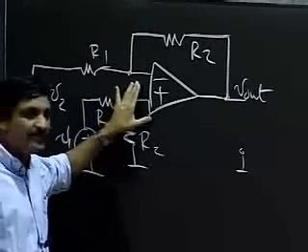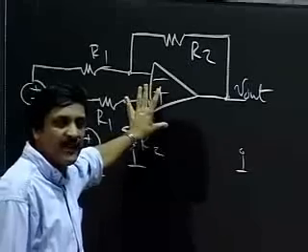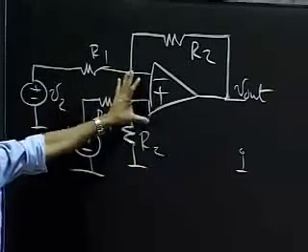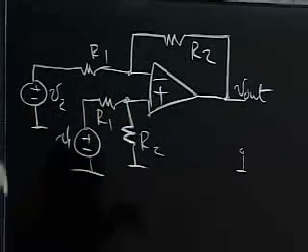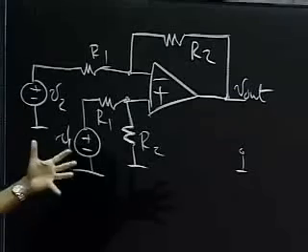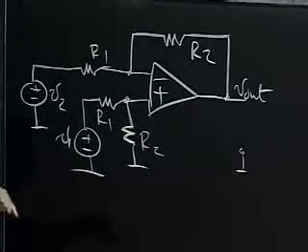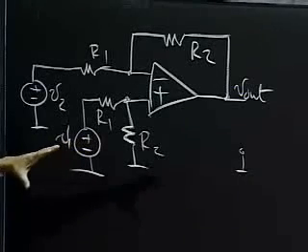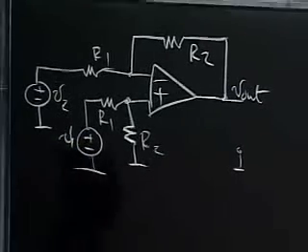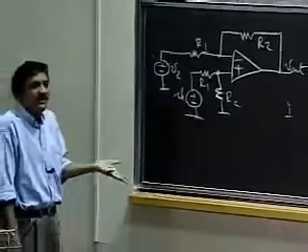In the last lecture, the technique I used to analyze op-amps was one in which I replaced the op-amp with its ideal model involving a dependent source and so on with a large gain, A, and I wrote the expression, and then I let A increase to infinity and took the limits and got an expression that was independent of A.